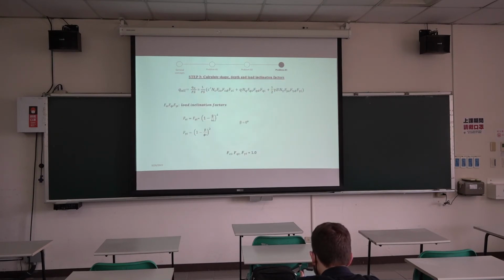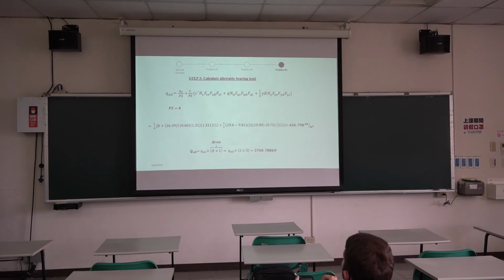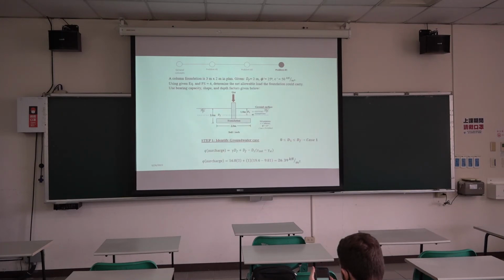Another equation of interest that also touches on that is this gamma. Because this gamma, normally for the bearing capacity equation, is the unit weight of the soil below the foundation. Okay? So if we look at this figure, below the foundation, what is the unit weight of this soil? It's below the groundwater, right? So if it is below the groundwater, we have to get the effective unit weight, gamma prime.